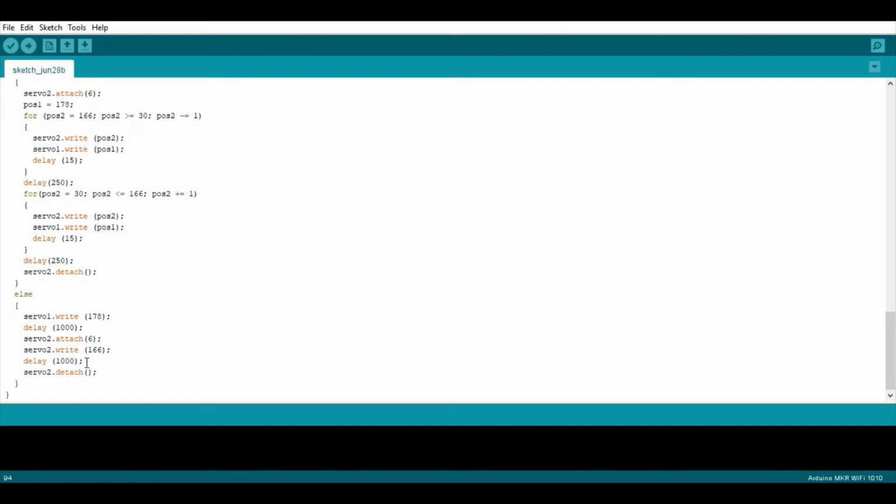So here I have basically explained the first flipping procedure of the two servo motors. But in our machine the servo motors only flip the object, not the plate. Meaning after doing a flip of 180 degrees, it also comes back to its initial position. That's why we need this else statement here.